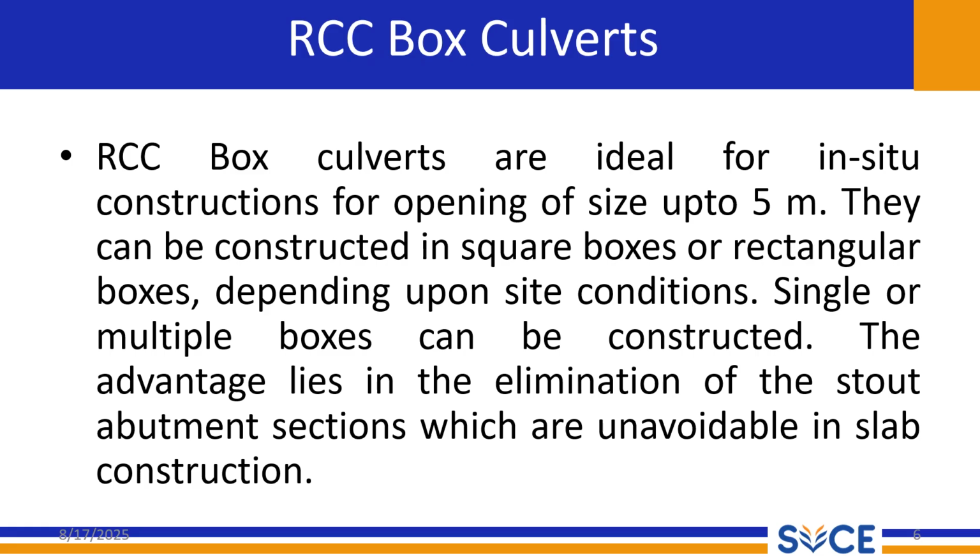So next one is RCC box culvert. The RCC box culverts are ideal for in situ construction for openings of up to 5 meters. They can be constructed as square boxes or rectangular boxes depending upon the site conditions. Single or multiple boxes can be constructed.